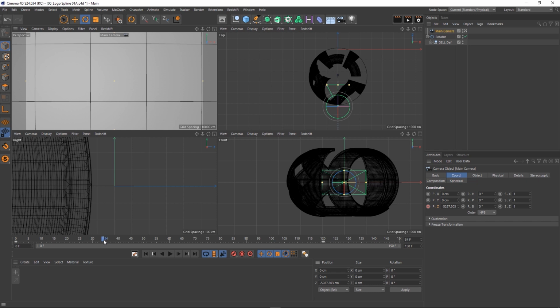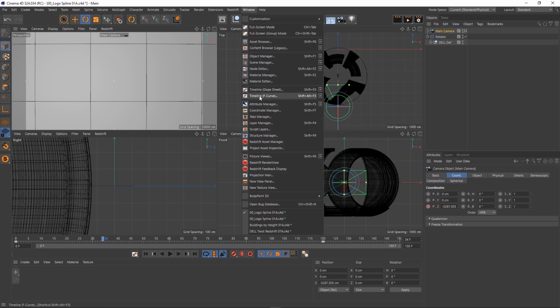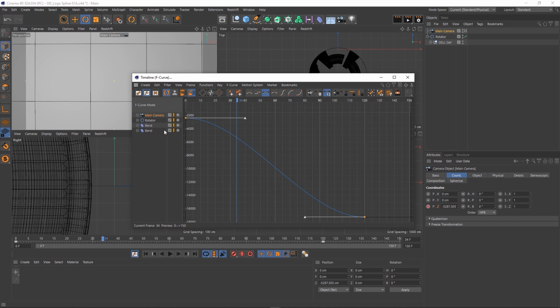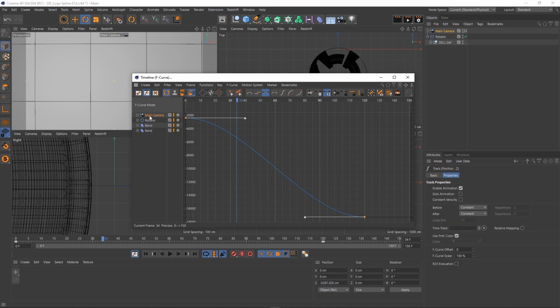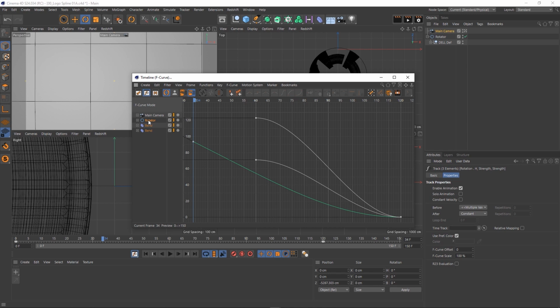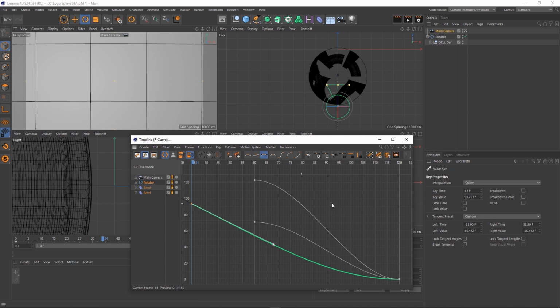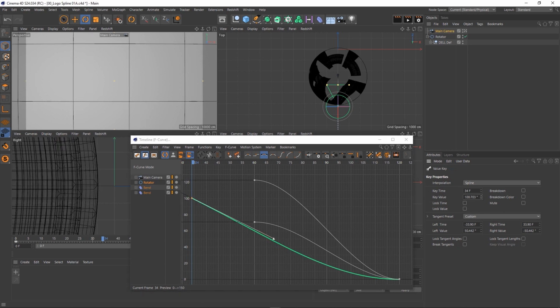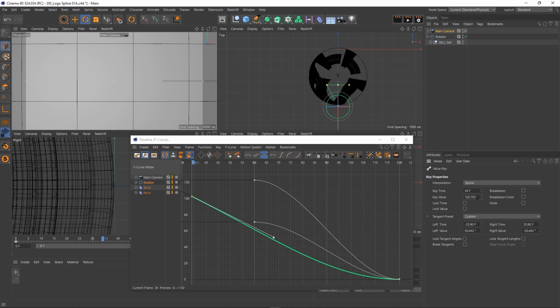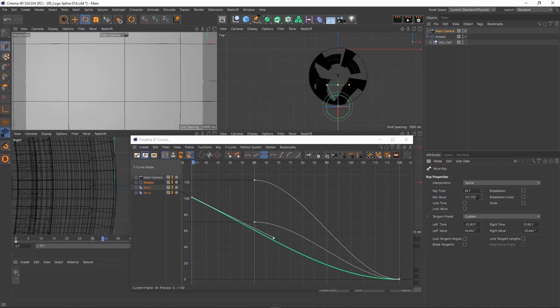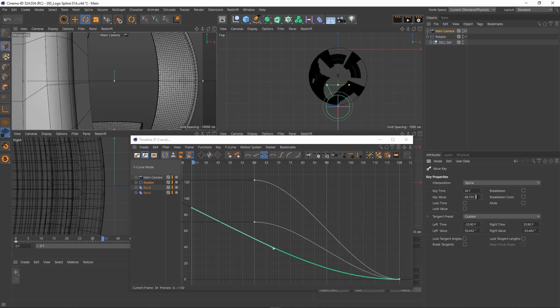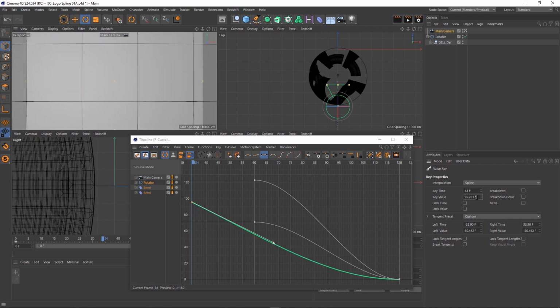So what I'm going to do is just leave my playhead over here, go back to my timeline, and I need to select my camera animation or my rotation, actually. And you don't see anything because you need to press H. And you can see that my rotation now needs to be adjusted, only the first frame, so that we are avoiding this geometry, whether you want to push it one way or another. So I want it to go the other way. I want it to go to the right. So I'm just pressing my down arrow on my keyboard, and I was going the wrong way around.